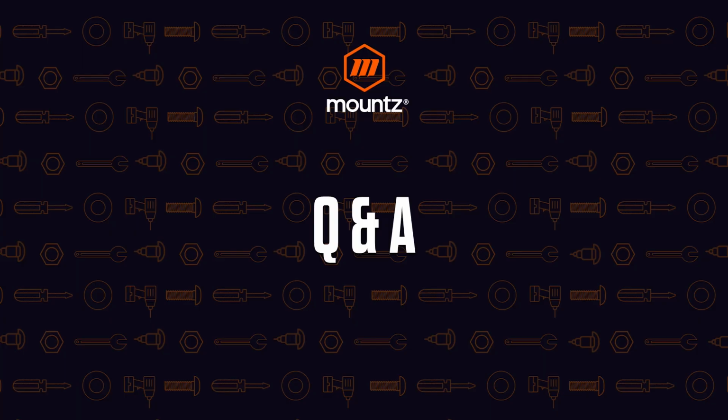All right, Dave. Another question we had is, if we're using a flexible adapter on the end of a torque screwdriver, will it have the same effect as when you're using an extension on a click wrench or any type of wrench? So if you're using an adapter on a tool that keeps the drive in the same orientation, so you're changing from a quarter-inch drive to a 3/8 inch drive, and you're using that type of adapter.